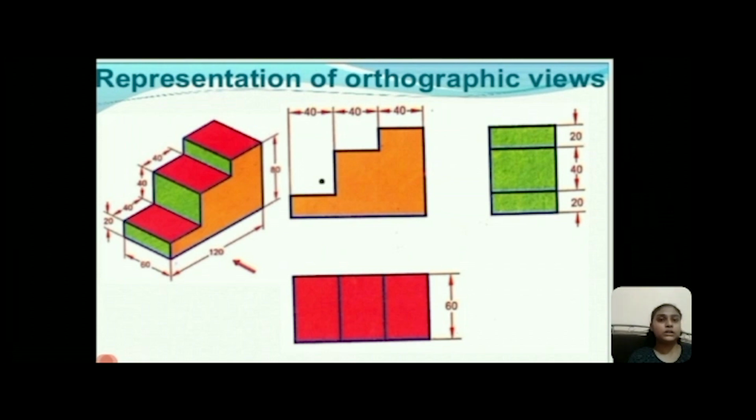The left hand side view is on the top of the XY axis. The left view is on the left of the object when you look at the front from the outside of the object. Likewise, for the front view, the projection view is obtained by drawing perpendiculars from all the points on the edges of the part to the plane of the projection.